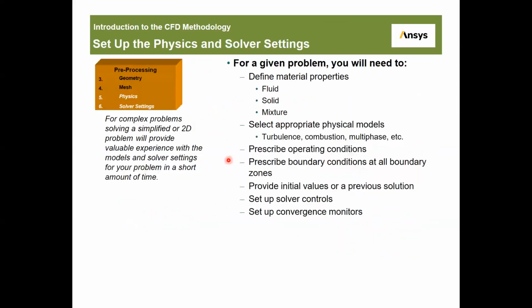So I think number five, physics. Set up physics and solver settings. For a given problem, you will need to define material properties, whether it is solid, fluid, or mixture.